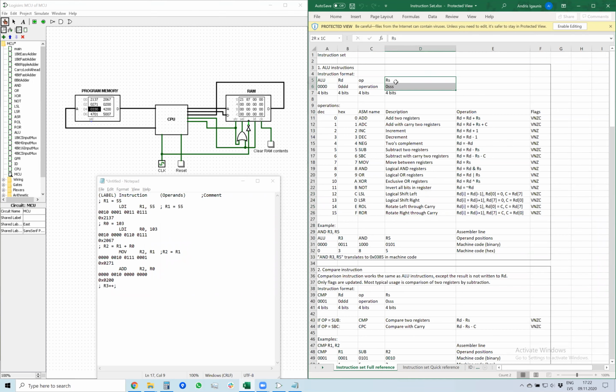So the final 4 bits are don't care bits. You can put any value in them, all ones or all zeros, they'll just not be used. They'll be discarded by the instruction decoder. So you only need to care about the first 3 nibbles, and the final one is, for example, all zeros.